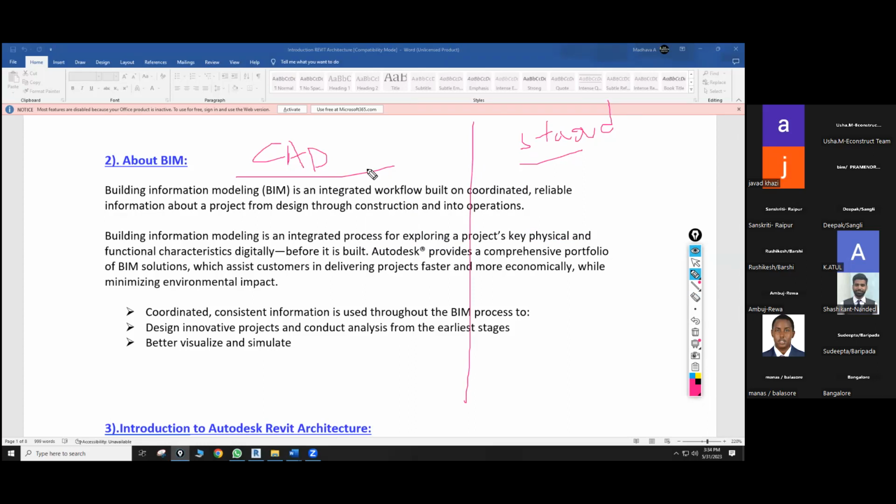So I'm going to start with my box. There is some obstruction at the ground level. Maybe there are water lines or some pipelines or whatever it is, some obstruction there when we are digging and excavating the site. Ultimately, we cannot disturb any water pipelines, water streams, or any such system, because that is government property. We can't disturb that. In case we need to change it, we need to take the authority's permission.